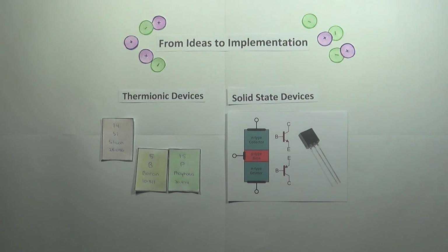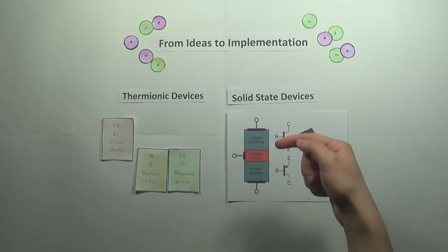The transistor operates on the basis of a p-n junction. A p-n junction consists of two joined pieces of an n-type and p-type semiconductor and acts as a diode. A typical transistor consists of two p-n junctions in close proximity, with a piece of either n or p-type semiconductor sandwiched between two pieces of the opposing type of semiconductor. These regions or layers are known as the emitter, base, and collector layers.